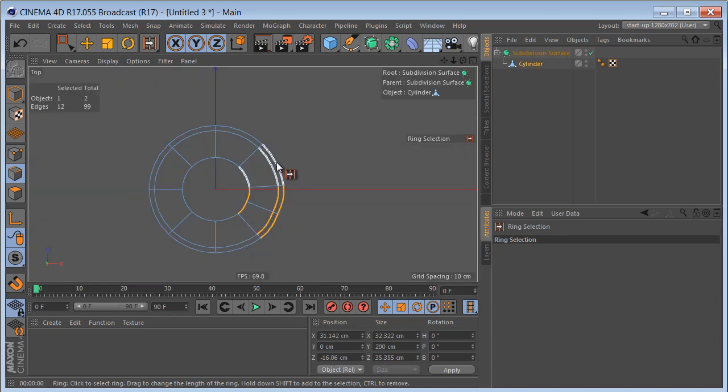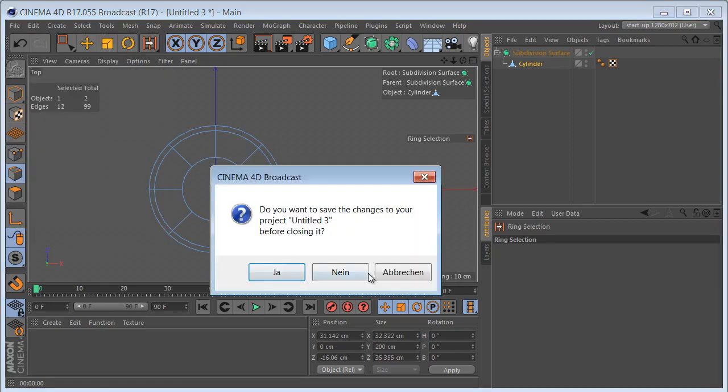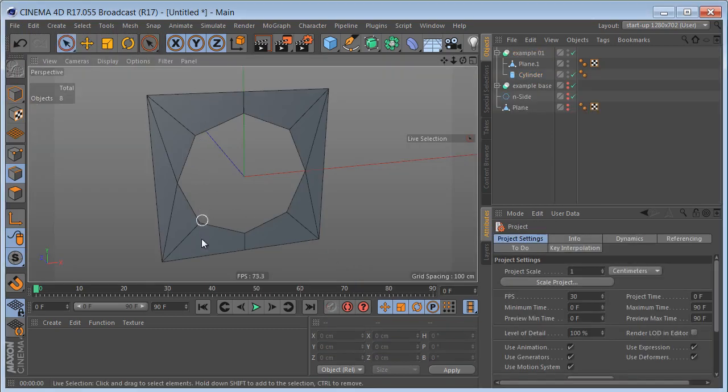And that's the problem with round objects like these ones. We need to keep the segments even to make sure the shape stays the same. That's why I want to make sure that these segments along the height are even. We can add as many additional edges horizontally as we want. It will not change the circular shape of the object when we wrap it around a circle spline, but it's very different with the height segments.